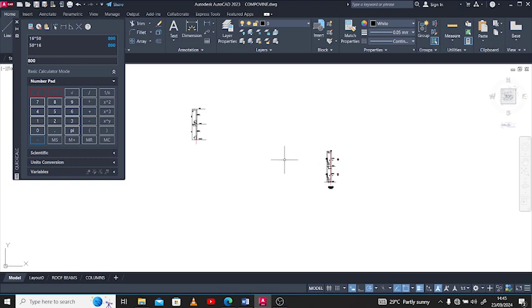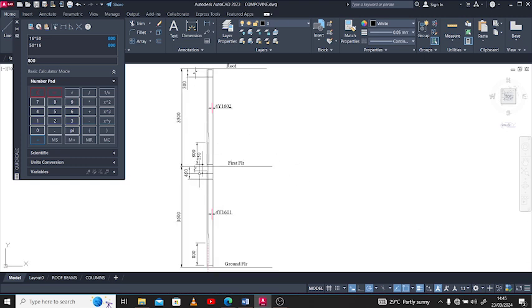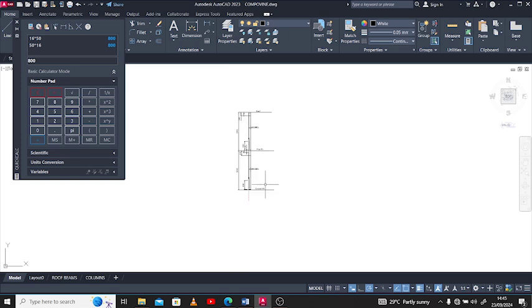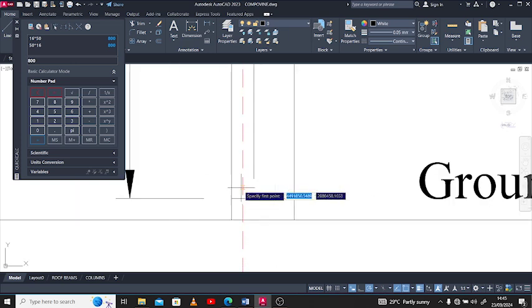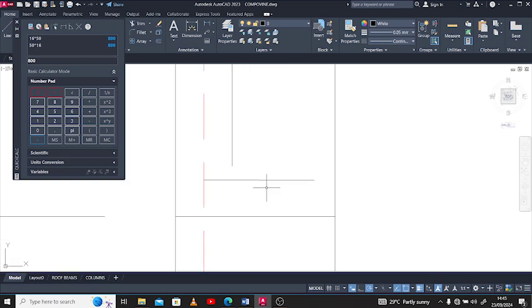Now we can put in the links reinforcement, the links detail, which we call the stirrups. So from here, about 50 above the face of the kicker, we can have our stirrup just there. Let's just do 50.